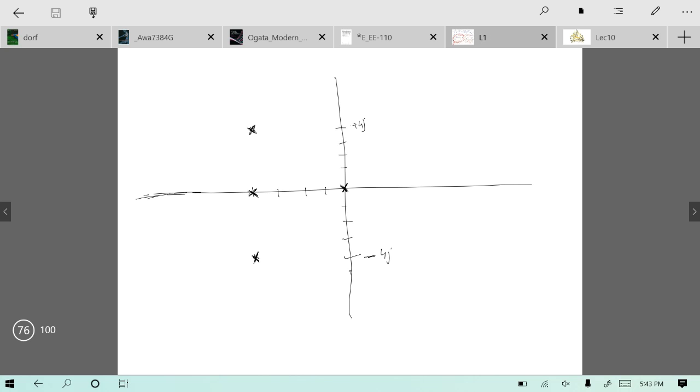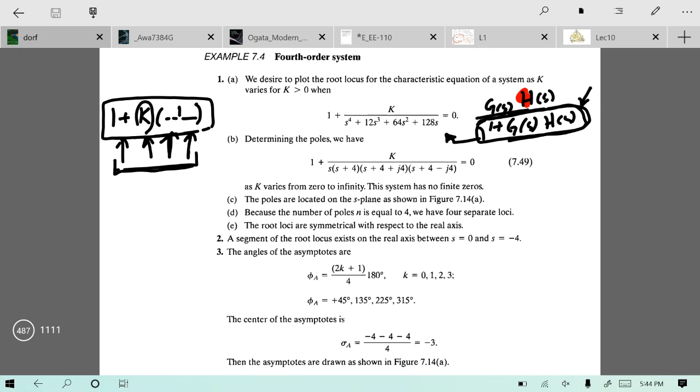So we have just started from scratch to draw a root locus. First of all, see, as there are four poles, when you change k, all four poles will change their location. It means you would have four loci. You have four parts of the root locus. This root has its own path, this root will have its own path, this root will have its own path, and this root will have its own path. So the overall root locus will consist of all of these four paths.